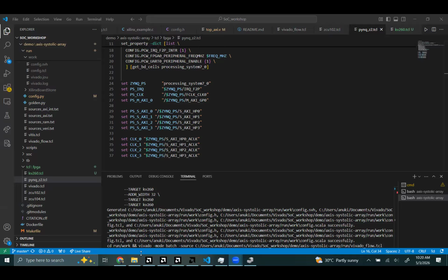And then the Tcl scripts you write to automate the GUI, you keep them as simple as possible, right? Previously I used to write several hundred lines of Tcl scripts: create a DMA, configure the DMA with different parameters, create floating point units and use them, all that. But then I realized that's a really bad idea when you go from one version to another, and Xilinx is not a very good software environment, right? So keep the Tcl script as small as possible, like we have shown in the README.